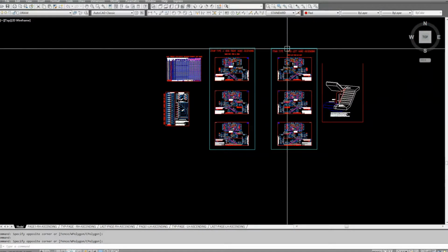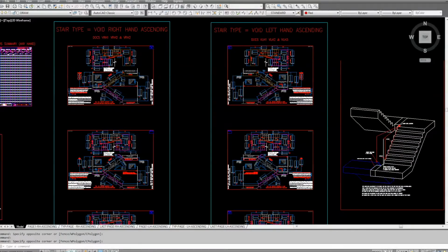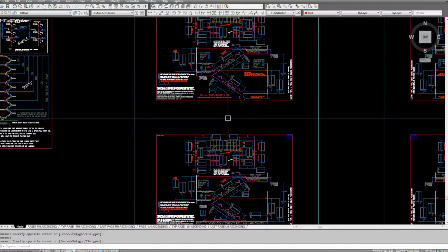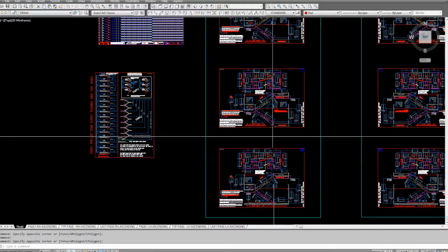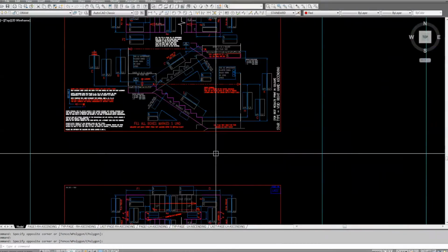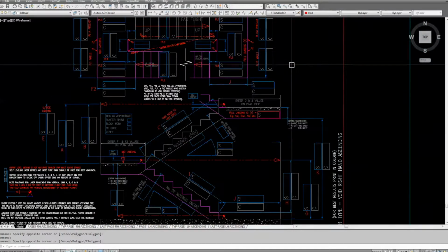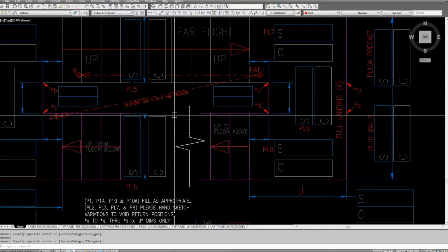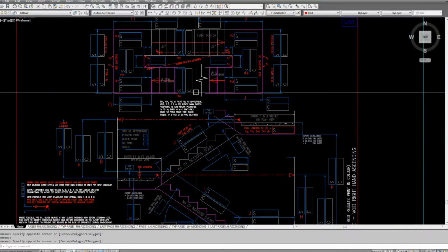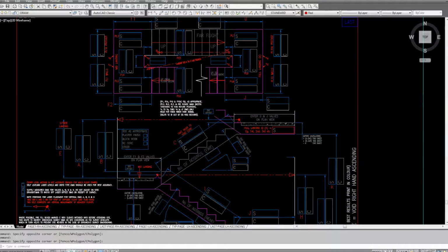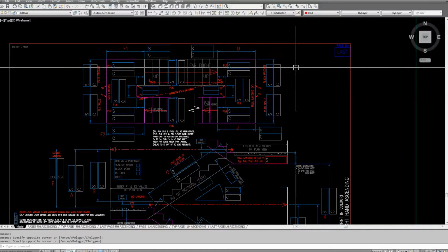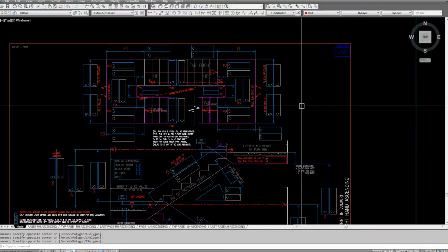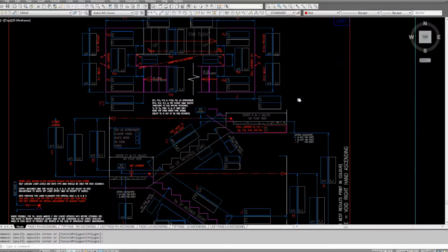So that's pretty much the information that I work from. If somebody's asking me, can I model some balustrade onto concrete stairs, and they're going to measure it, I'll pretty much insist that they use this method. As I say, it looks very convoluted, but it's not. Once you get your head around it, or if you see one filled in, it isn't. It's a really good and methodical method. It also ensures that you get all the dimensions that you require, because if you've got an empty box, how hard is it just to glance over a sheet of paper and see if you've got any empty fields?